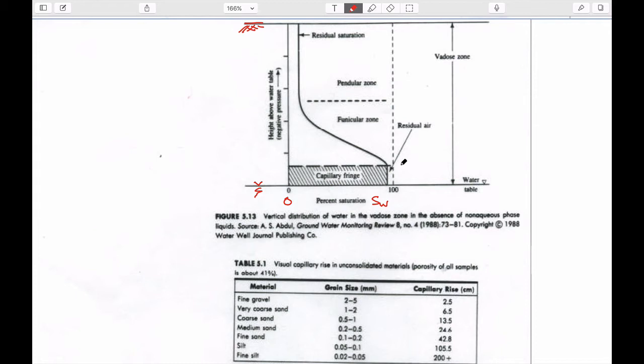The physical meaning of this, what we've often called a bubbling pressure, PC0. If we divided that by the unit weight of water, then this would be a height. And this physically would be the height at which you can hold the water up. It's in tension. By definition, at the water table, the pressure here has to be atmospheric.